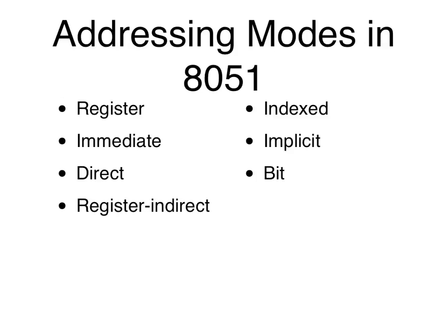Okay, just a quick summary of the different addressing modes in 8051. So you've seen register addressing, you've seen immediate, and remember immediates refer to constants, right? They're part of the instruction stream. And direct addressing, that means it's an address that is right after the opcode. And so that's a hard-coded address.